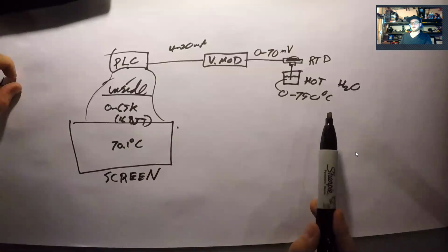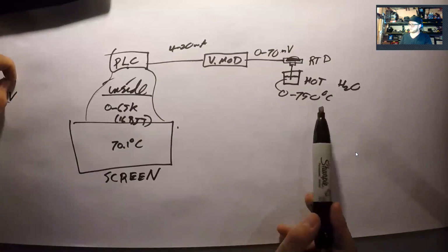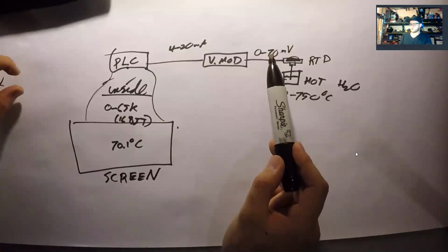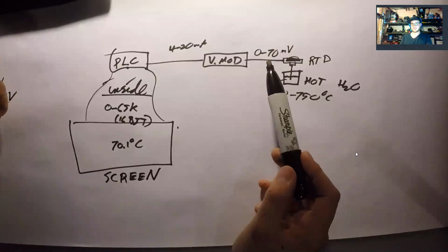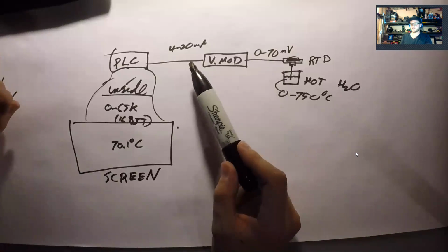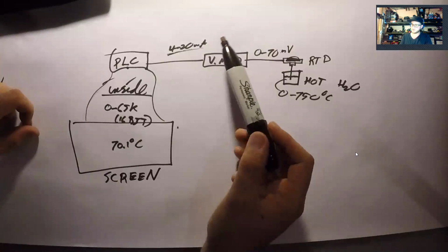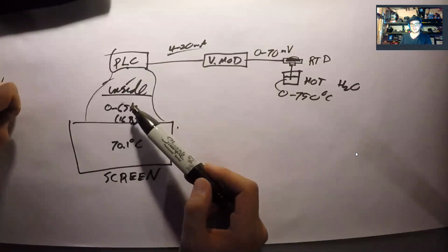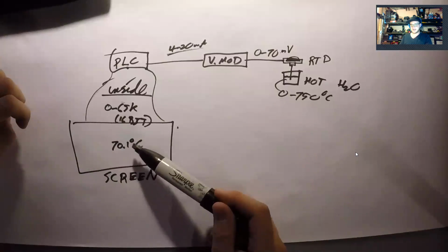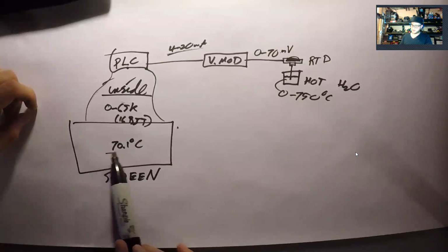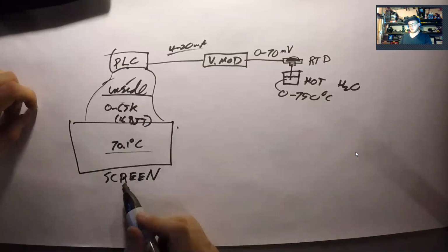And so you see here, there are all these translations that happen through our train, from the physically measured value to some analog value that's an electric signal, which then gets translated into our standard analog control signal, that then gets digitized into some digital value that then gets translated out to the end user.